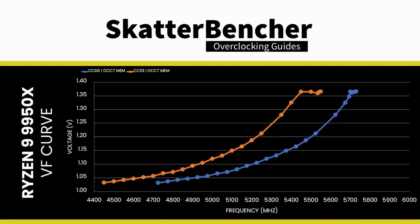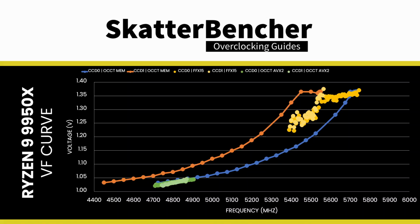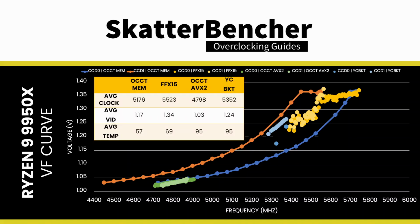To better illustrate my point, here are the final VF curves of this overclocking strategy. I'll add the voltage frequency points during three workloads: Final Fantasy 15, OCCT AVX2 CPU stress test, and Y-Cruncher BKT. You can see not only do the points diverge significantly from the VF curve, but they're also at totally different parts of the curve. The average frequency, voltage, and temperature during Final Fantasy 15 is 5.5 GHz with 1.34 volt at 69 degrees Celsius.